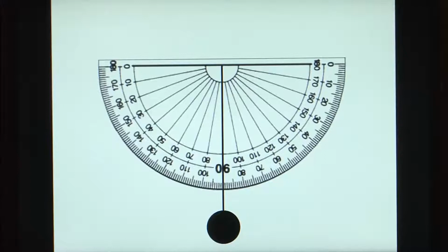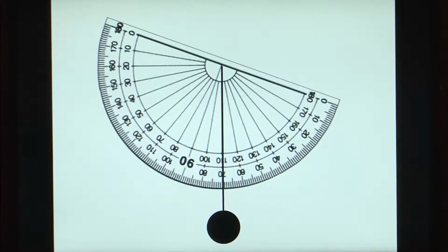So, what we have done here is we have taken a protractor and right through its 0 point we have drilled a hole and put a string through it, and on that string we can suspend a weight. Now, if a weight is suspended, then this string is always held vertical. So, now if this protractor is moved to measure any angles, it can be used. Let us now see how it would look in practice.